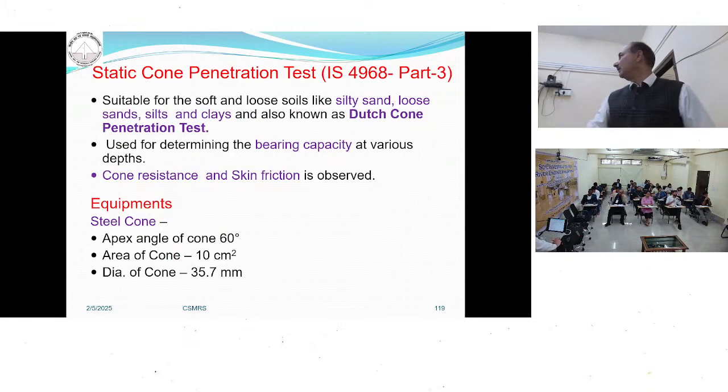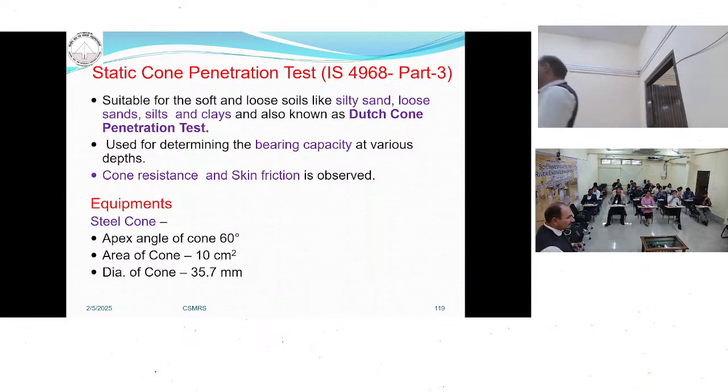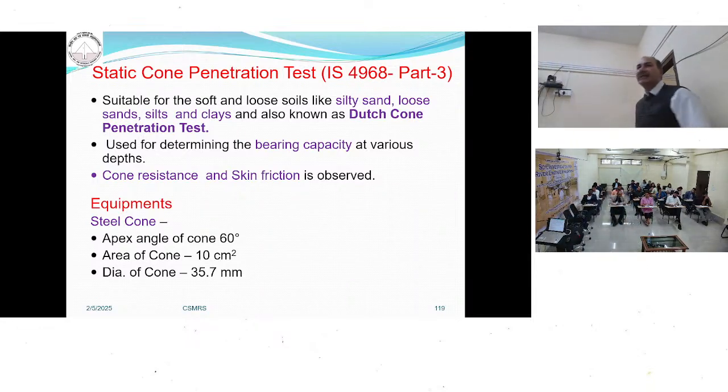Next one is the static cone penetration test. This is a very good test, and it is applicable for both sandy and clayey soil. The benefit of this test is that it gives us the cone penetration as well as the skin friction.